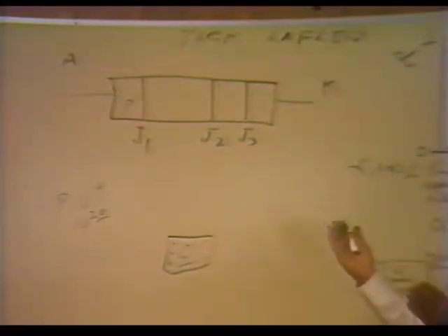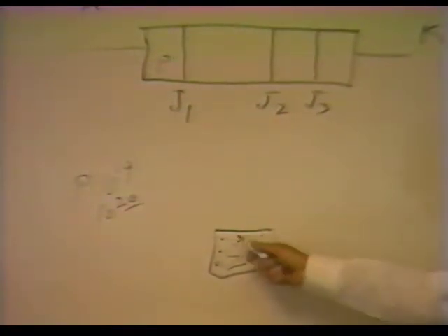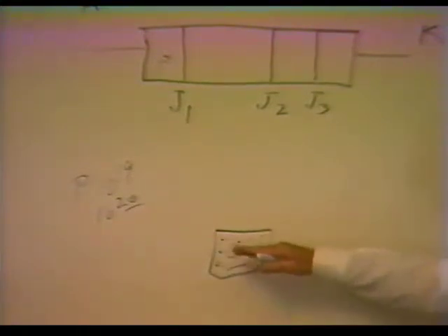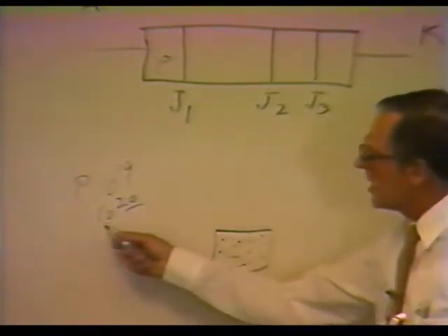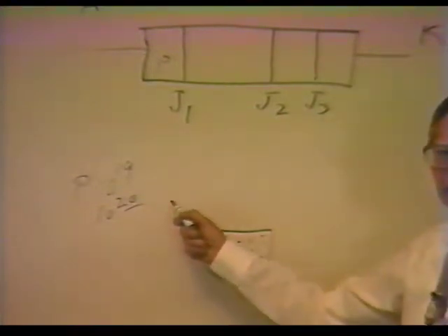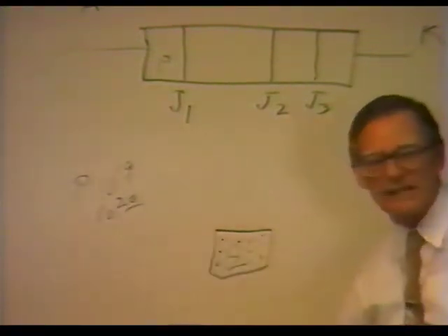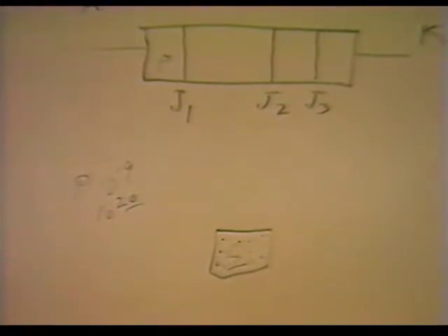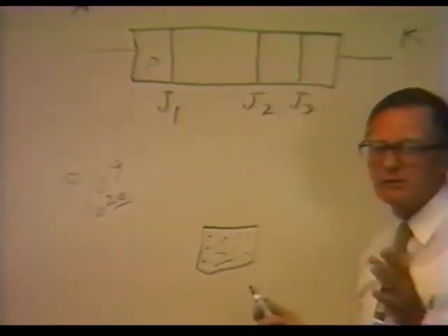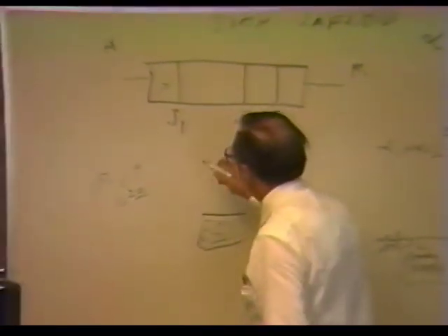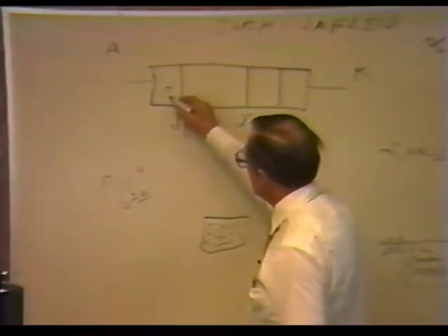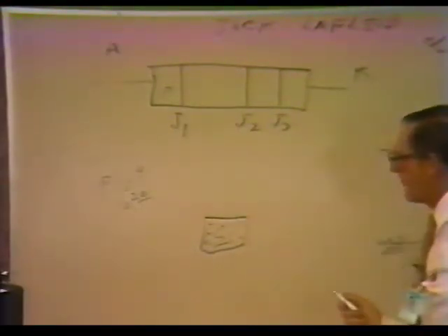They're not put in a uniform manner. The concentrations can be heavier in certain areas and lighter in other areas, but by and large, if you were to count the number of impurity atoms in it, it would be 10 to the 19th, 10 to the 20th per cubic centimeter. Now, that is a fairly high doping level for an SCR. So that's a fairly highly doped P region.